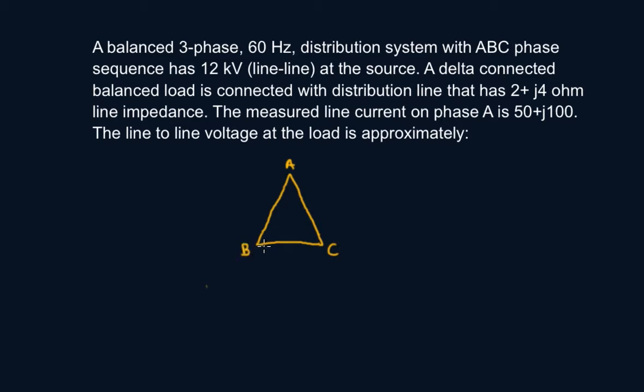Normally what I do with these problems, I highlight in my head, or you can highlight in the problem, your keywords. We've kind of said that already: three-phase is a keyword, ABC phase is a keyword. The line-to-line voltage is given, not the phase voltage. The delta load is a delta, not a Y connected.